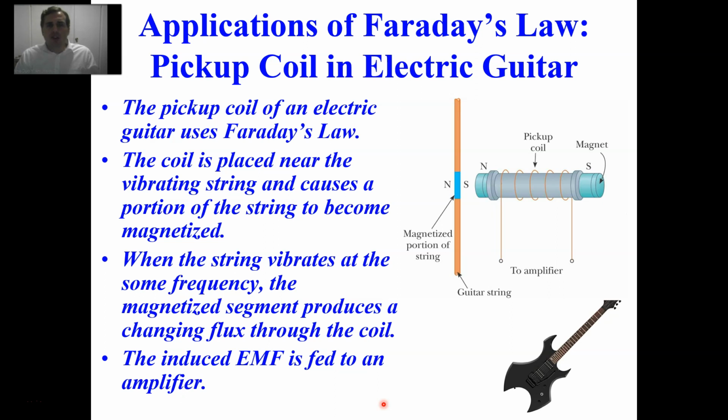Here's a nice application of Faraday's law: a pickup coil in an electric guitar. Here is a depiction of a guitar string, and there's a small portion of the string that's magnetized. When you vibrate that string, this magnet is going to vibrate back and forth, and we have a magnet with a pickup coil around it. As the guitar string vibrates, you're going to change the electrical signal in this pickup coil, and that's going to go to the amplifier.